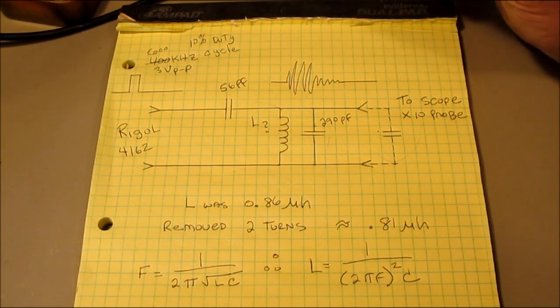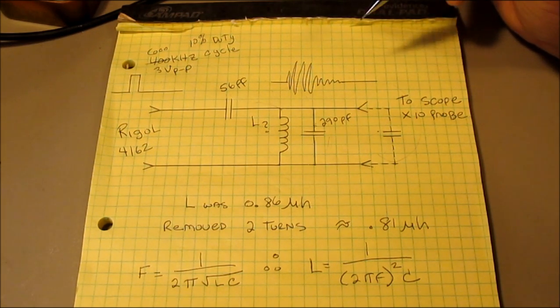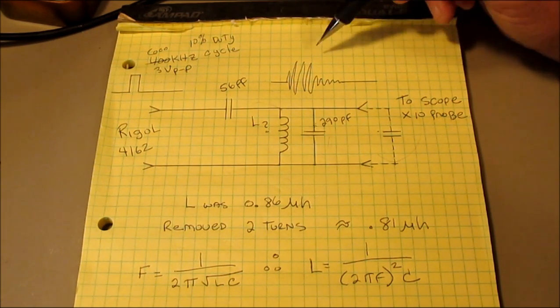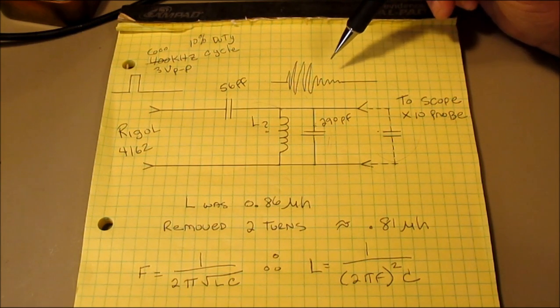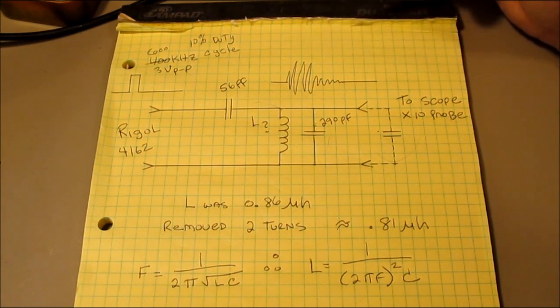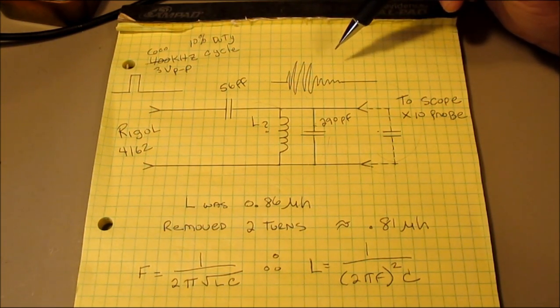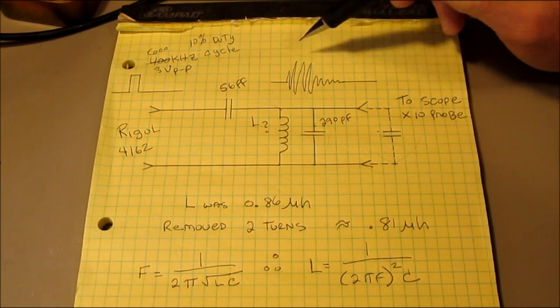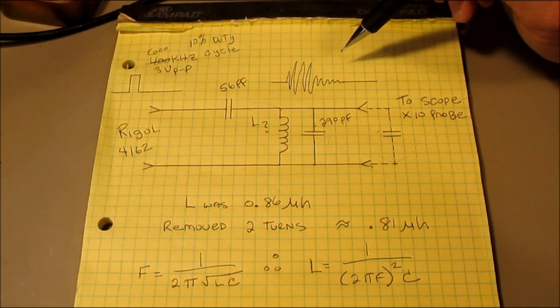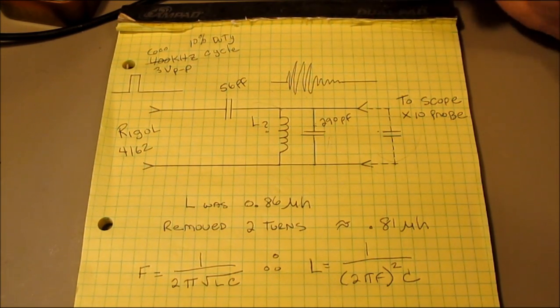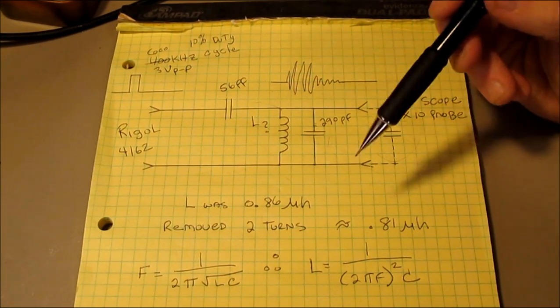And in the case of my scope, I'm using a Rigol DS1102 for this, and there's a measure button, and when you press that and press display, it'll display all the characteristics of that waveform, including the frequency, which is what I'm going to do. You can narrow that down with the scope to whatever specifics you want, but it was in this case just as easy to do that. And the waveform looked a little nicer than the one I drew on the paper here.